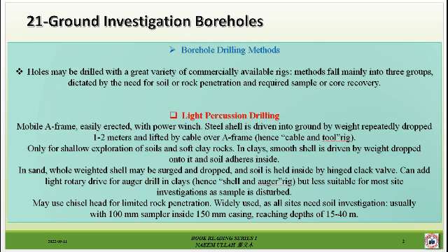May use a chisel head for limited rock penetration. Widely used as all sites need soil investigation, usually with a 100 mm sampler inside 150 mm casing, reaching a depth of 15 to 40 meters.